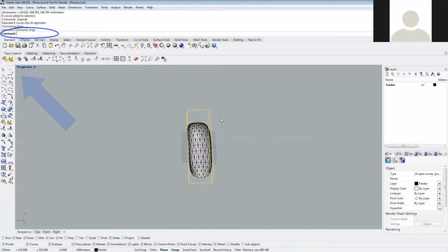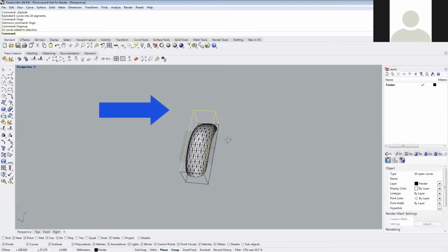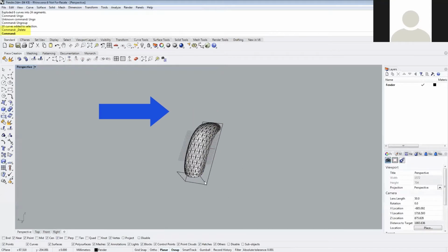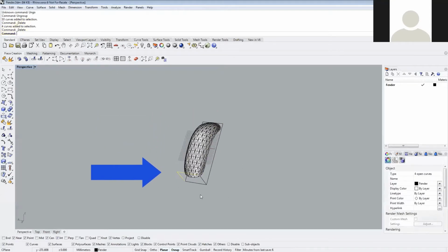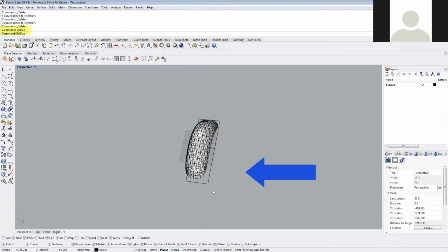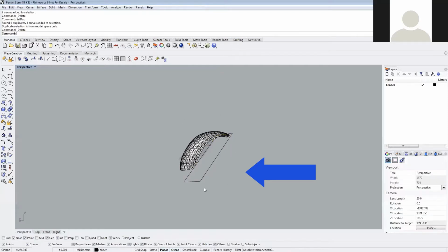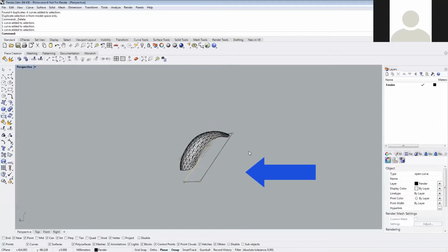So we're going to use the ungroup command to ungroup these curves. This allows us to select and remove the curves that aren't needed. So we'll remove those. We're going to remove these as well. Remove these. And I'm also going to use the cell dupe command to select the duplicate curves here. Each face of the bounding box is going to have a separate curve there, so we always have duplicates. But once we remove them, we have just these curves down here.